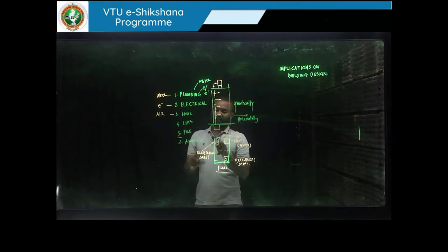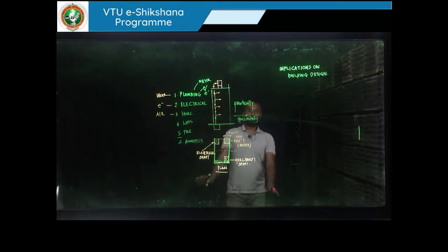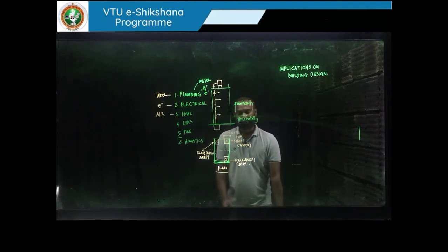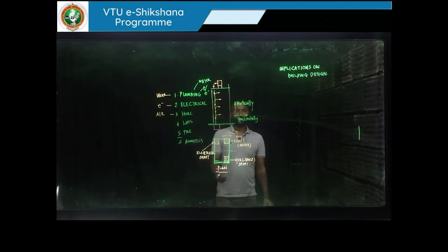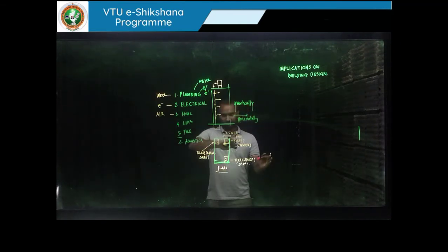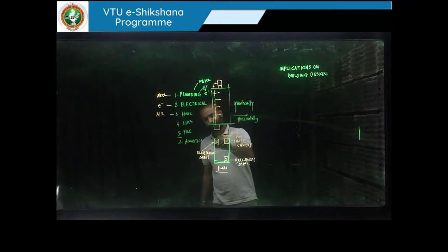So imagine a case where we have a separate electrical shaft, separate HVAC shaft and PHE shaft. If there is any mishap here, it is contained only there. Of course, I'm not saying we are avoiding every possible problem just by separating them, but we are avoiding the main and important part of their interaction, where we can still contain some of those unprecedented circumstances.